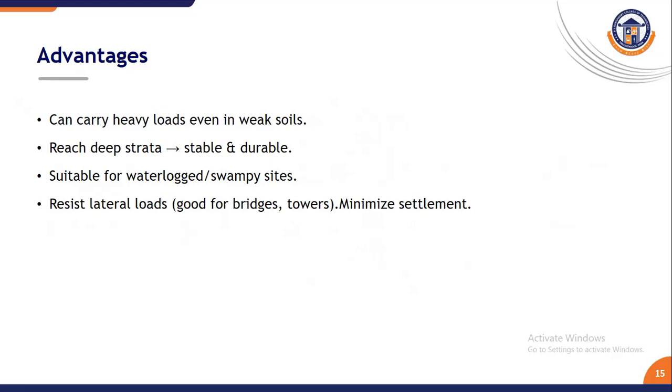And then overall, the main merits of using the pile foundation are that it can carry very heavy loads even in soft or swampy soil where shallow foundations fail. They also have the ability to resist horizontal forces, making them suitable for bridges, towers and tall buildings. Moreover, they reduce the risk of uneven settlement, ensuring that the structure remains stable and serviceable over time.